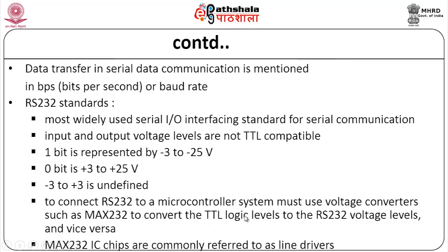That conversion is definitely needed, then only it can be interfaced. For that purpose, people use IC chips commonly referred to as line drivers. The MAX232 or MAX233 are the IC chips commonly used